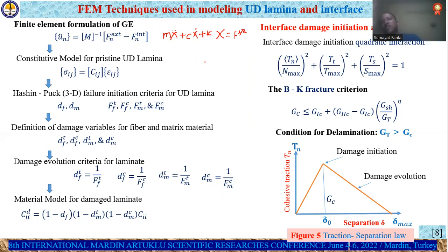So using the forward Euler method, we will find the mass inversion. Okay, so this is the explicit finite element method, so we do the forward Euler iteration method to determine the parameters like acceleration, displacement, and velocity. So this equation shows the forward Euler technique of finding parameters. Okay. So on that, the constitutive relation is also defined in terms of stress-strain relation.